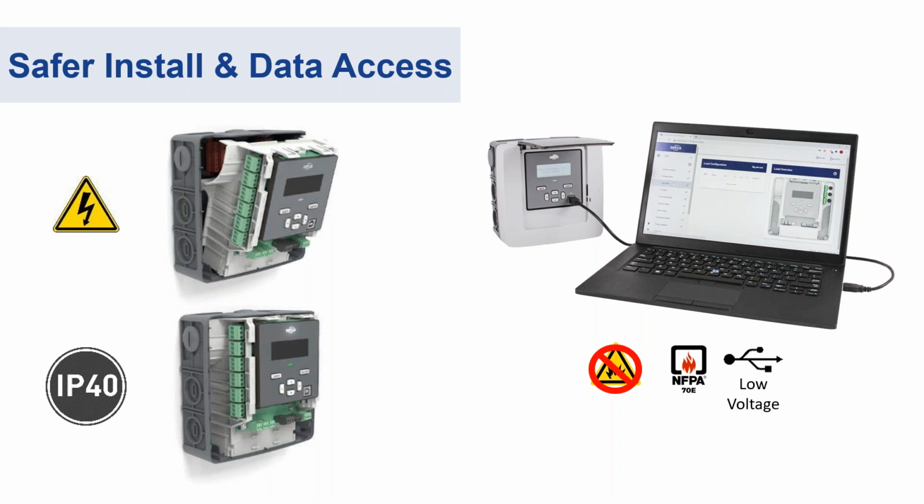Okay, I'm going to start with the last one. If CTs are wired backwards, you can switch the polarity in the software itself. So just connect to the meter, either IP or USB, and then modify, just slide that slider, and that CT polarity is corrected. You don't have to go into the panel.